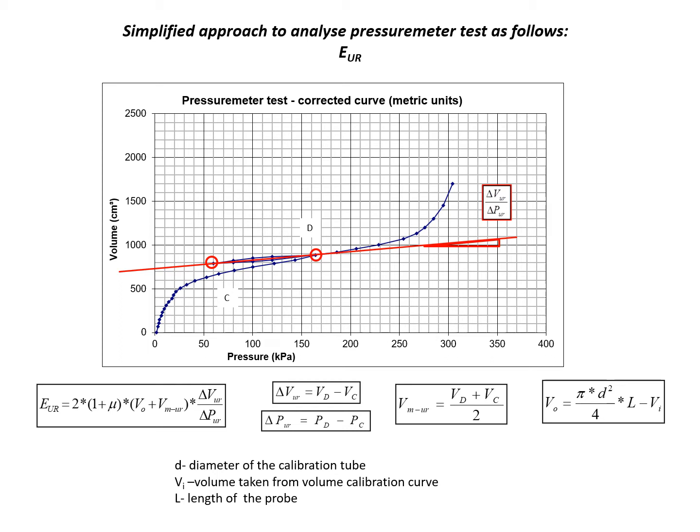What I would like to suggest to you, because many consultants or some engineers or textbooks suggest that if you have this rebound, they calculate the unloading, reloading tangent, and then some average. I couldn't understand, except for theoretical approaches or modeling, how can I use it? So I keep it simple. If it's rebound, I just take 2 points, or between if it's not exact, and calculate some average tangent. That's it.